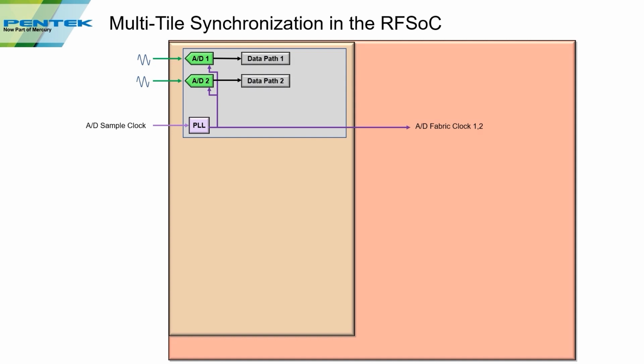The next thing I want to draw on the block diagram is the output of the A to Ds. These are the parallel outputs. I'm calling here the data path as the interface to the A to Ds, and then that feeds into the FIFO, and the FIFO sends the data out into the fabric. So that's the main signal path for each of the A to D channels.